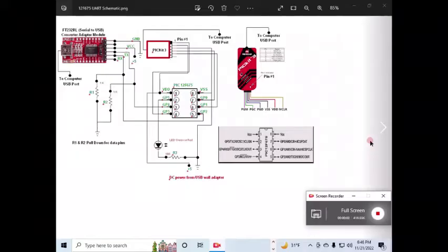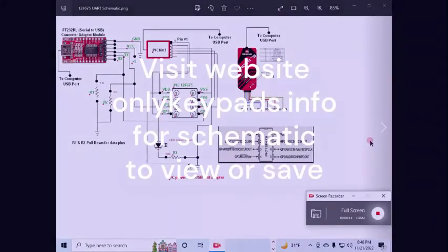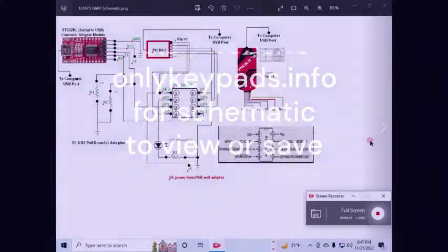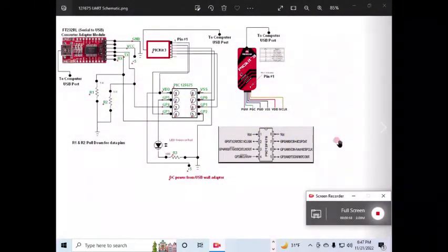This presentation is going to demonstrate how to communicate with a UART connection between a PIC microcontroller and a PC running the Tera Term emulator software. I'm only going to be using the TX data line for this demonstration, and the PIC I'm using is the 12F675.